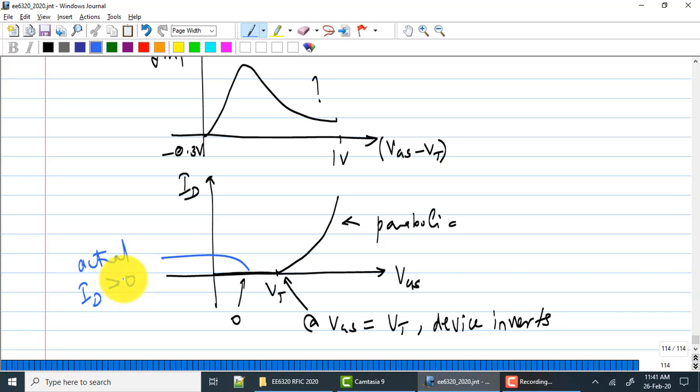You may remember this. Then it hits depletion, because VGS is becoming larger and larger. P-type charge carriers get kicked out of the channel region. And you assume that at some instantaneous voltage it inverts. But unfortunately, that does not happen.